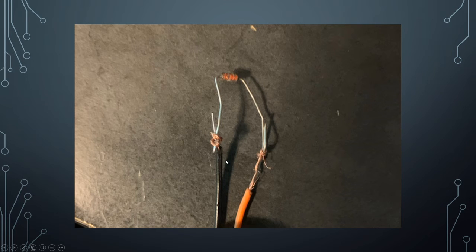These leads on the thermistor were not thick enough to fit in the female leads on the wires. So I stripped the end of the wires, curled them up, twisted them together, tied them up as best I could to keep the best connection there. That way it wouldn't give a false reading because of resistance from not making a good connection or anything.